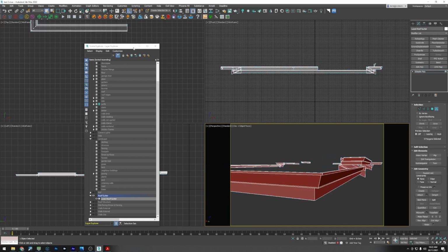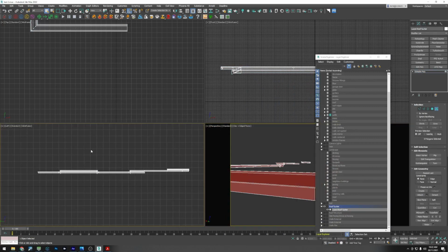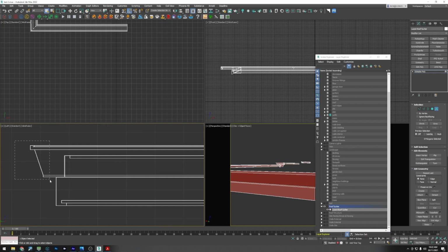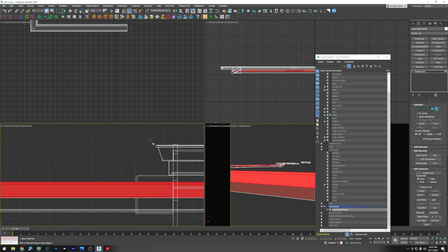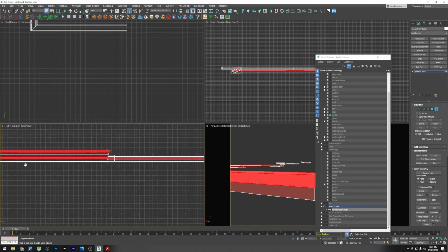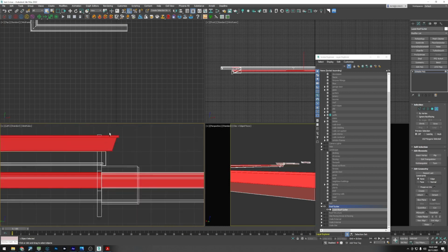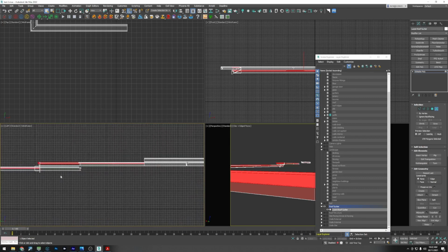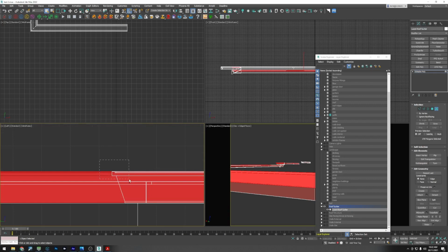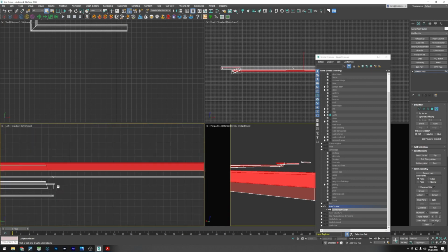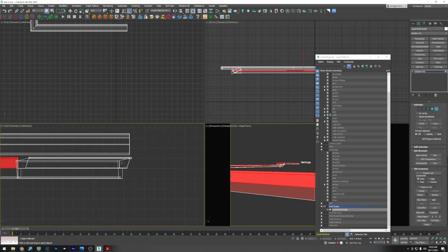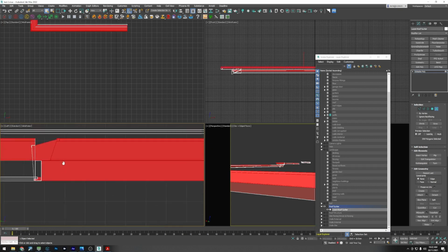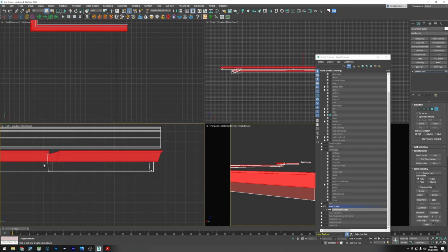The easy way of doing that is usually in the left or front viewport, and you can just go in and select the gutters by themselves. You can see here it's easy to select those that are kind of overhanging. Select that there. Just go around, select any that are easy to get in this way. And there. Looks like there's one there. There. That one's selected part of the fascia, so we're just going to alt click that.